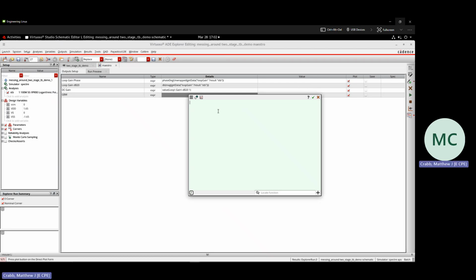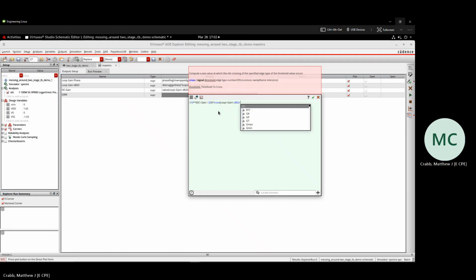let's see, I need my DC gain in volts to volts. So let's do 10. Exponent is 2 asterisks. So 10 to the DC gain divided by 20. Then that's going to be times, and my bandwidth is going to be the point on the loop gain.